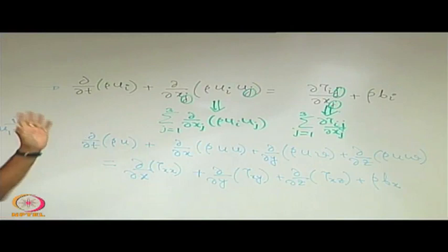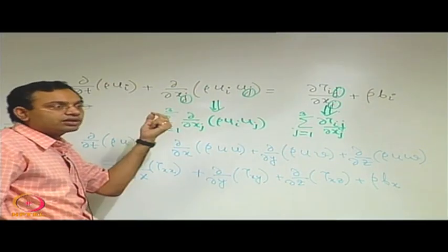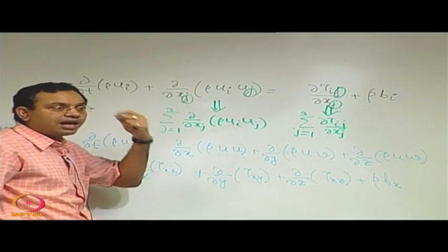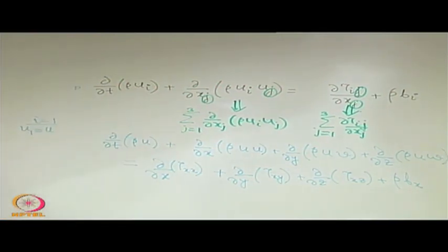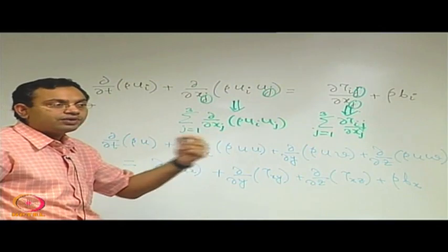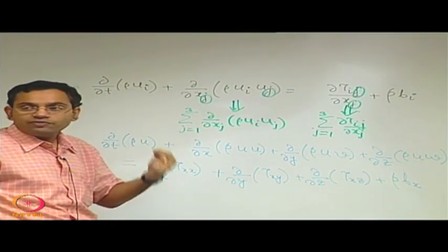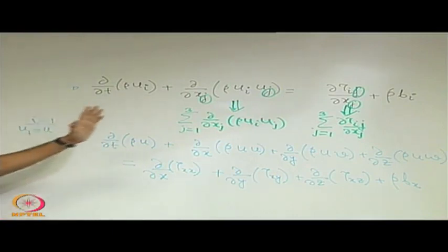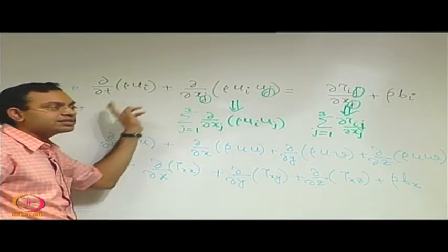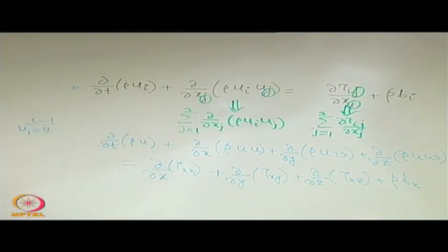So acceleration of the flow is related somehow with the transience, that is the unsteady effect, that is, at a particular location if things change with time, and if there is a change because of the change in position from one point to another point where the particle finds a new flow field, that is the advective effect, and the combination of that is the total derivative. We will be able to express this in terms of the total derivative, that we will do subsequently.